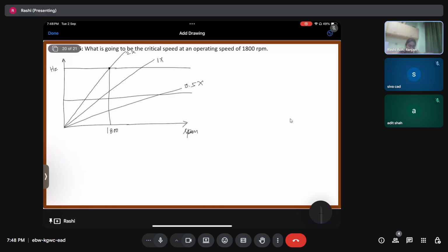Now, if we don't have any idea about the natural frequency of the system, we can give it an operating speed that may result in very high amplitude oscillation. When we are talking about a motor or any kind of rotating equipment, having an ideal system with homogeneous and evenly distributed mass without any eccentricity is very difficult.